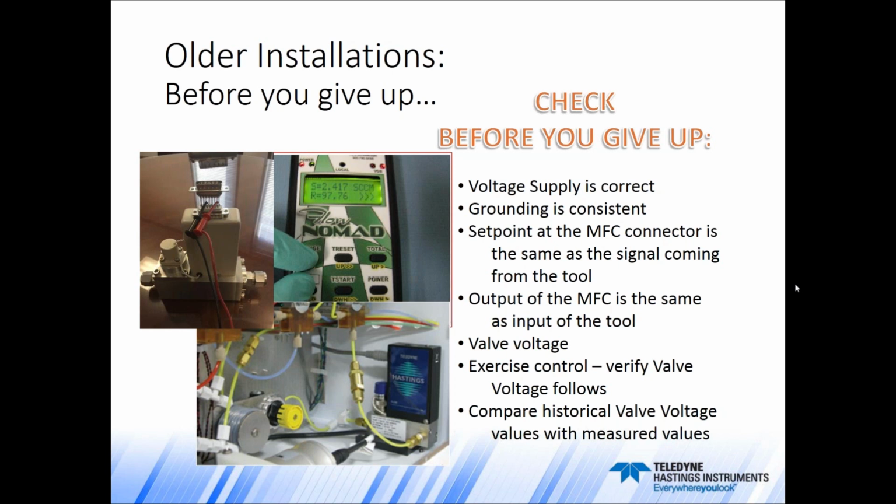So monitoring this parameter will tell you if changes have happened inside the flow path, or changes have been happening in the process that will force the MFC to struggle more for that set point that you deem necessary in the process control. So we recommended early on, for research facilities or production facilities that are using statistical process control, SPC, to use the valve voltage as a monitoring factor, along with set point, output, and output from different sensors in the process.